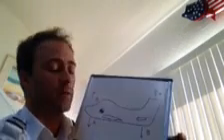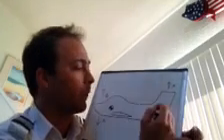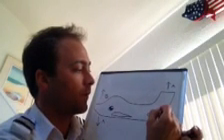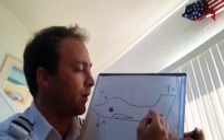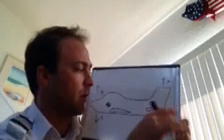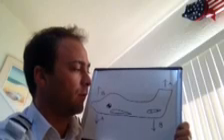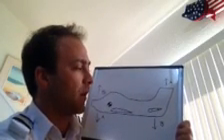And an anti-servo tab is located on a stabilator, which we've already discussed earlier. And a stabilator, when moved, the entire control surface moves because it hinges about a point which we can compare to a center of gravity. And that's how we can picture its movement. And the anti-servo tab actually moves in the same direction as the stabilator itself.